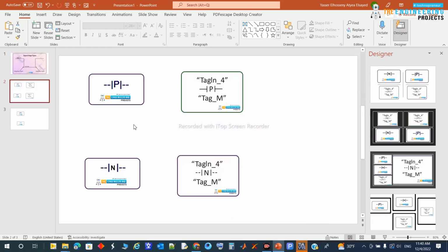So how is this symbolized in our logic programming? Here you can see it's simply a contact for the input, but I indicate that I am watching the edge, with P for positive edge or N for negative edge. But when you see the actual programming, you will see two tags, or two memory variables of type Boolean. So why do we need these two?